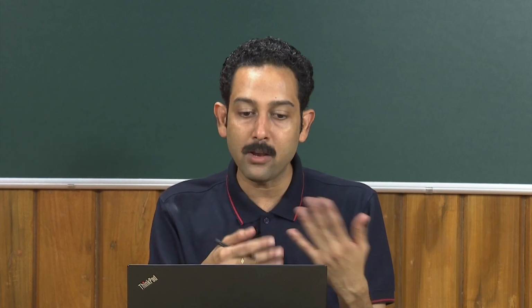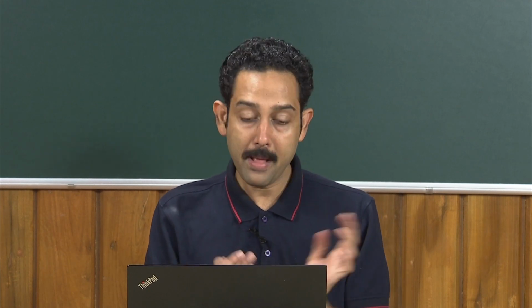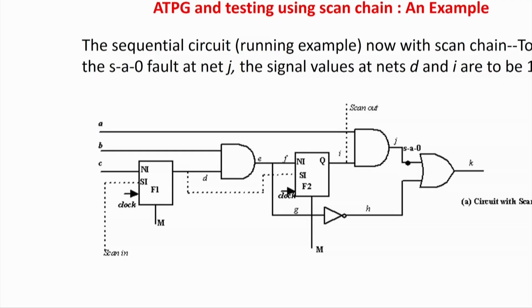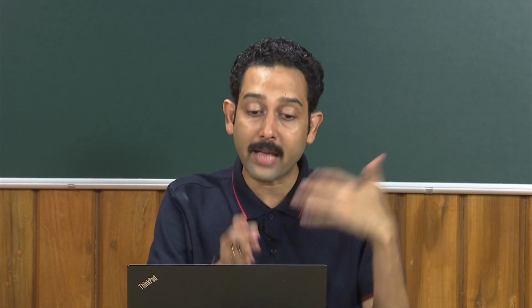It was a more complicated mathematical problem: if flip flops are intertwined without using any scan or set/preset, how can you get to the real values required in a very short amount of time? These are more mathematical problems, but nowadays nobody uses it because the story of scan chain has come into the picture. So I think you are able to appreciate that if you are not able to directly control the flip flops, you require more test patterns and also calculation.